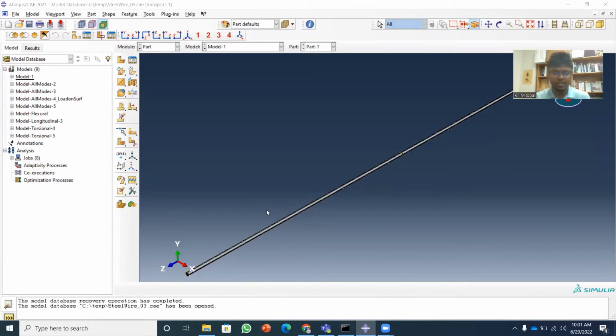So one of the major tools that is required in non-destructive testing is to understand how the different kinds of waves travel in materials. To understand that, sometimes we need to model in some finite element tools to see how these things actually travel in different kinds of materials. So I'm going to prepare some tutorials on how to model the wave propagation in different kinds of materials, also different types of waves like the longitudinal waves, the flexural or the shear wave, and the torsional wave.